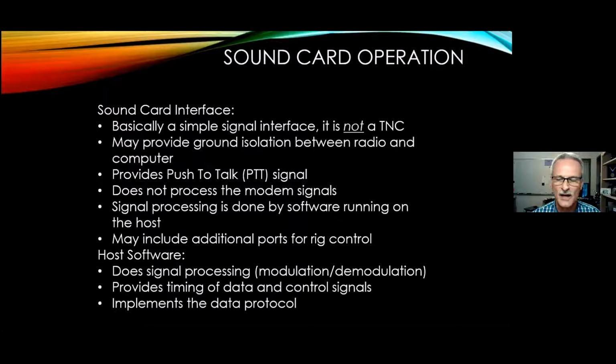A TNC does a lot more than what a sound card interface does. Some of the things, it may provide ground isolation between the radio and the computer, and I'm going to talk about whether that's necessary or even desirable anymore. Of course, it has to create the push-to-talk signal. We have to be able to put your radio into transmit mode, and that can cause us some issues sometimes, and we'll talk about that a little bit too.